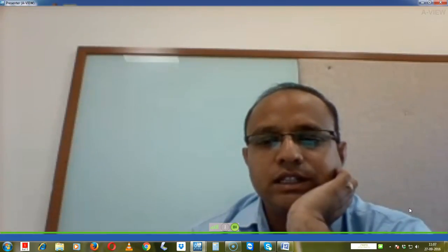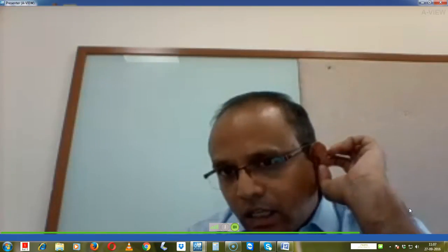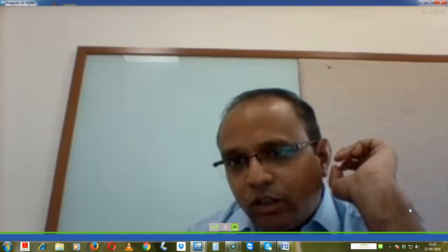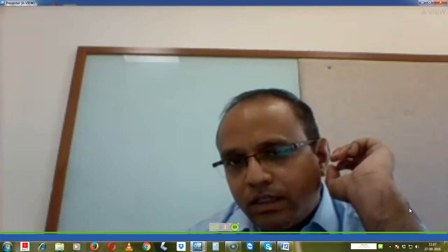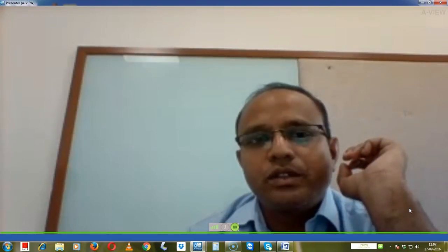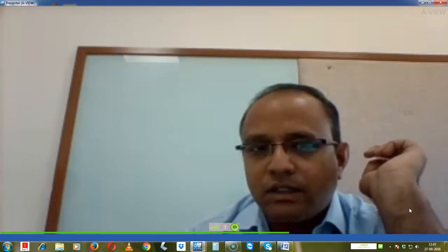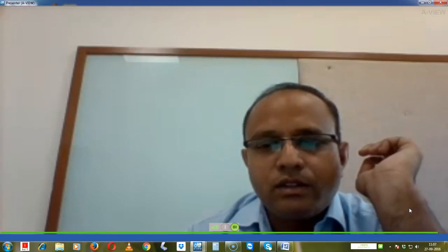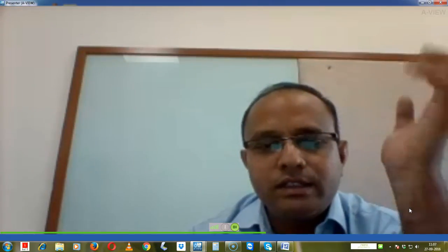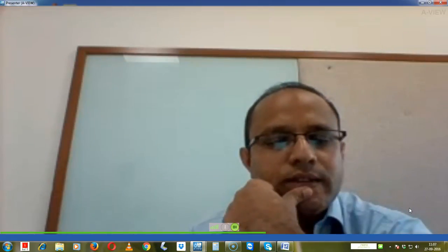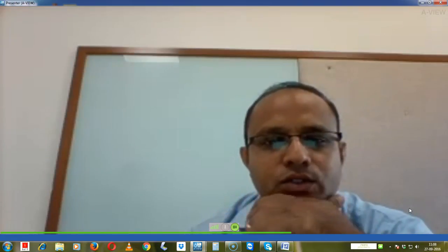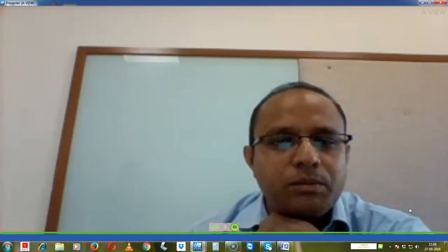Suppose this is the x direction and this is the y direction. This face is constrained in the x direction and this face is constrained in the y direction. The direction normal to this face needs to be arrested here, and the direction normal to that face needs to be arrested there. This is how boundary conditions are used to simulate symmetric bases as well. So this is one example. Again, we'll discuss in our loads and bases.